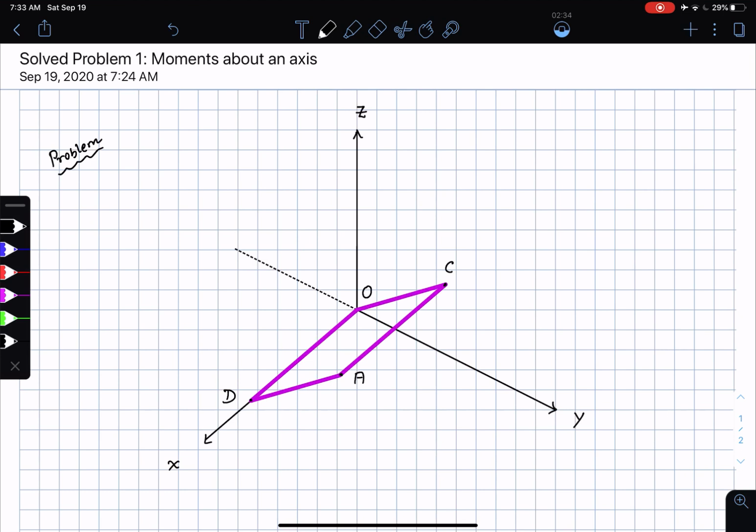I'm given some dimensions, and before I do that, I have a cable that is running from the point A all the way to a point B. Okay, so here is the situation. So here is the point A, and then here is the point B. Obviously if I have a cable, then the cable is going to be in a state of tension, so there is a force that is acting along the length of this cable. This force is given as having a particular magnitude of 200 newtons. So this is a force F, and F has a magnitude of 200 newtons.